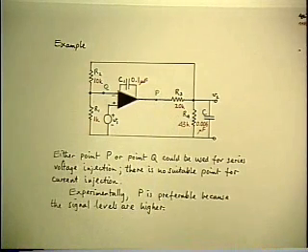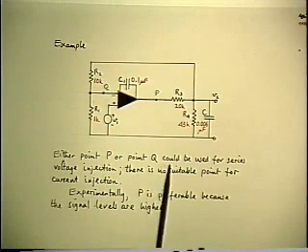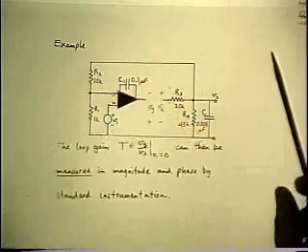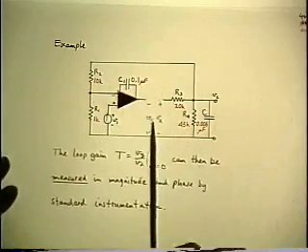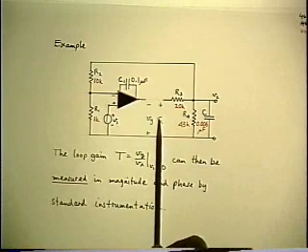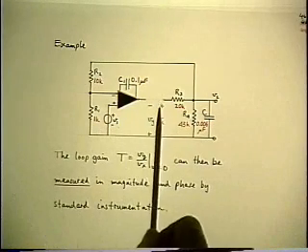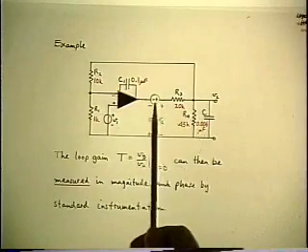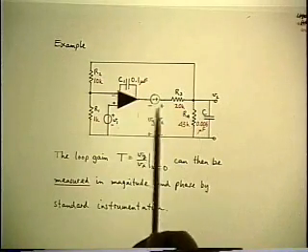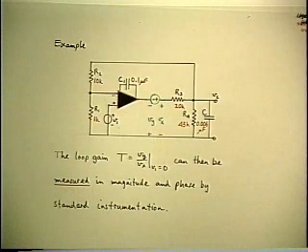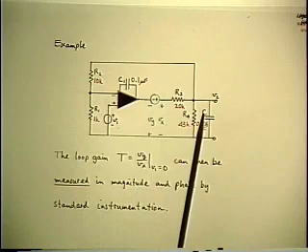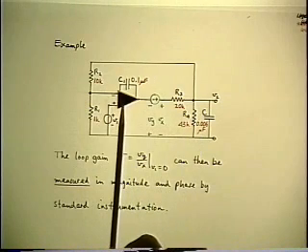So the first thing to do is the analysis, which means you draw the model. And after that, we'll be able to inject a signal, both on paper and on the bench, making the V1 0, and we'll have an injected voltage source at that point. That'll be the VZ. Okay, the circuit is explicit except for the gain of the op amp itself.